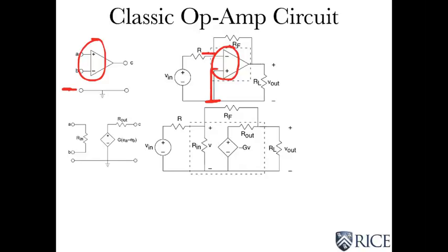Okay. So it maybe becomes a little bit clearer when we use the circuit model for the op-amp and stick it into our circuit. So the way that works, here's Rn, and we'll define a voltage V across it, and because the op-amp is plugged in upside down, the output is minus GV, where G is this big positive gain that I showed you in the previous slide.